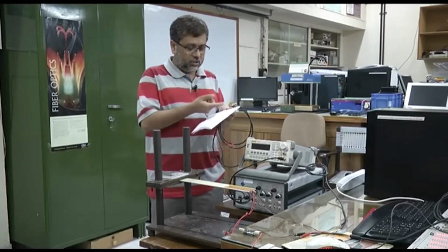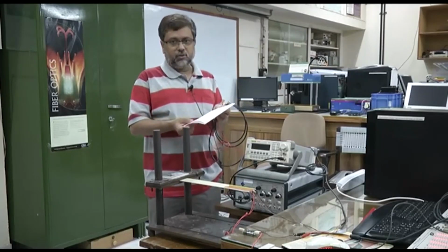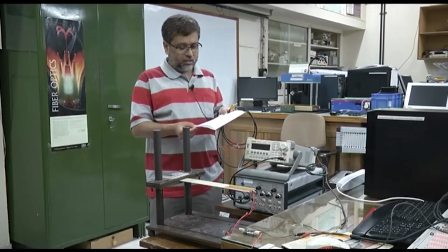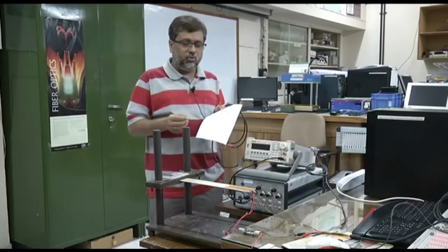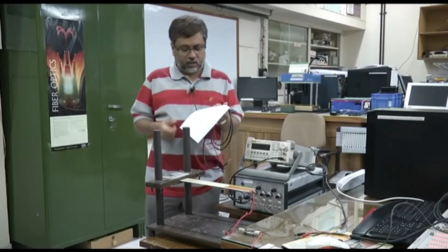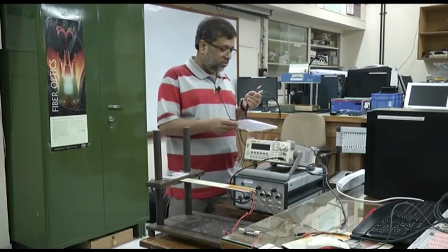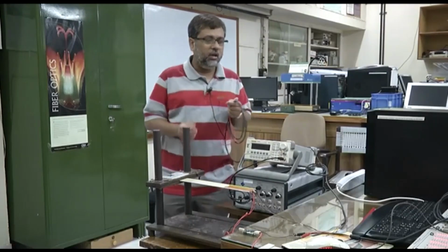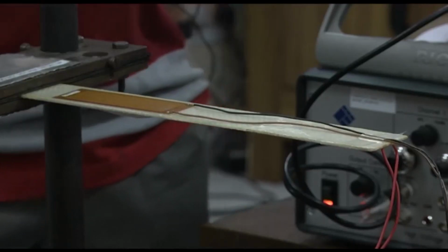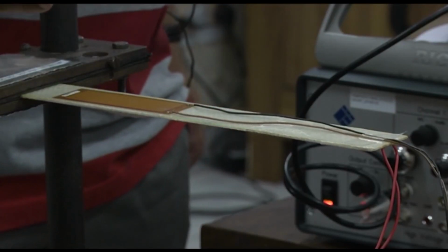The thickness of such a system is about 300 micrometers, and as an actuator it survives about 10 to the power 8 cycles, as a sensor about 10 to the power 11 cycles, and it can also be used for harvesting and storing energy, and in that mode it will last about 10 to the power 10 cycles. So with that, now I am going to show you how this system will work once I excite it. In this setup we are going to show how you can use a macro fiber composite MFC to generate vibration in a flexible beam.